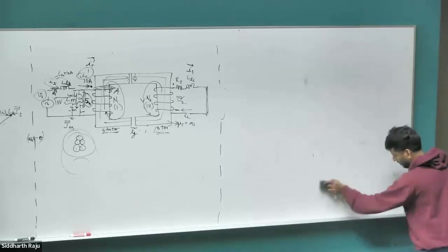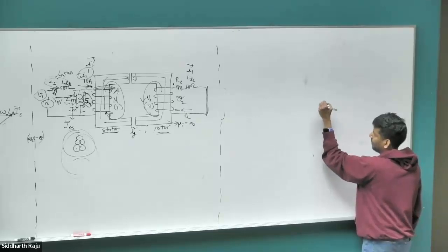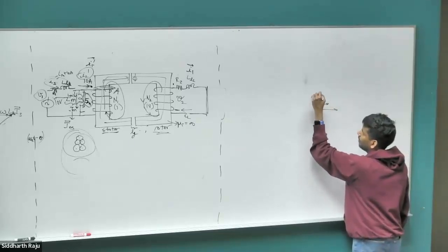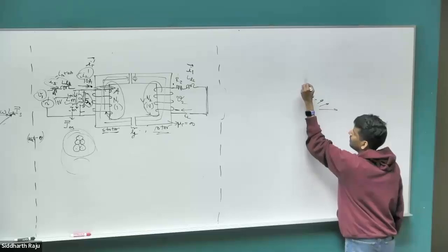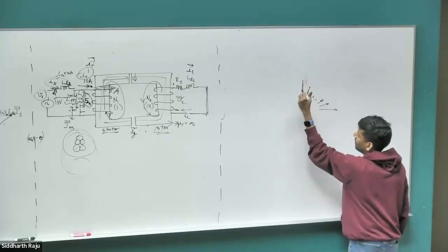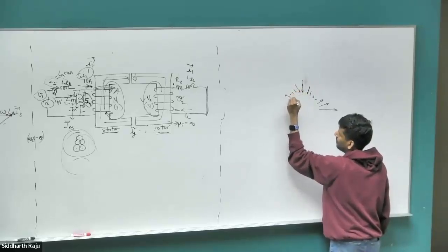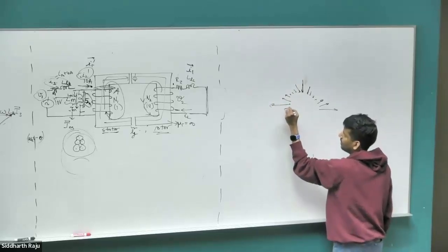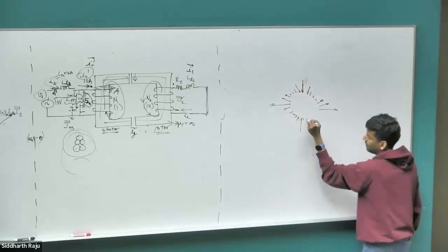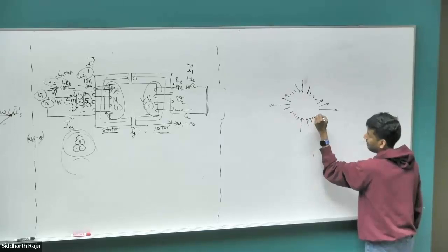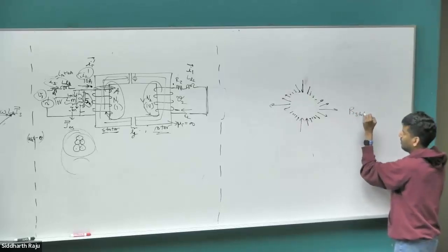Jack gave the perfect answer, because when you had 4 poles on the stator, what would have happened? You would have had a magnetic field peaking here and then going to 0 within 45 degrees and then reversing direction, having the negative peak here, and then reversing direction again. So you have this due to the stator profile.